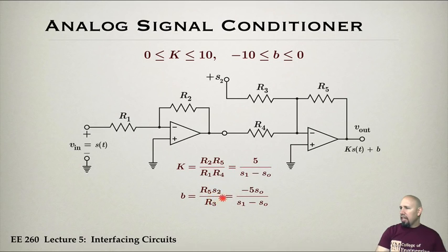Okay, then I can choose R3 to make this, and so forth. In other words, we can choose a resistor, so R1 and R2, to make this happen. Since I have one equation and 2 unknowns, I would choose, for example, R1 to be 10 kiloohms, and let's make these two guys 10 kiloohms. So all of these are like 10 kiloohms, and then R2 is going to be this times 10 kiloohms, and that's what we would choose as the value.